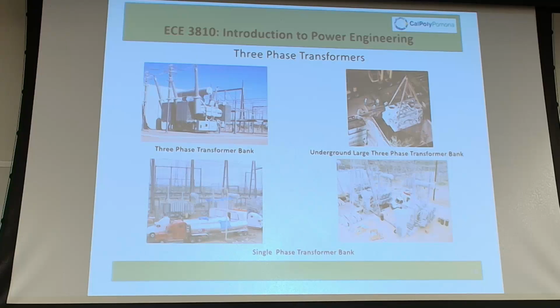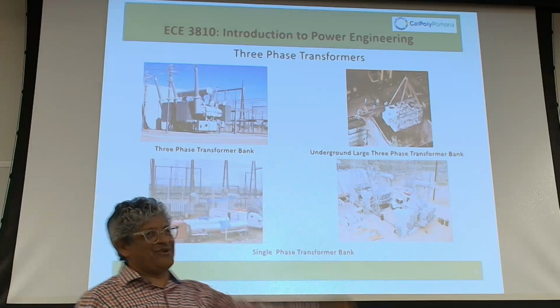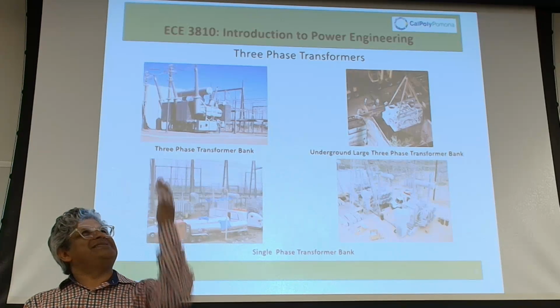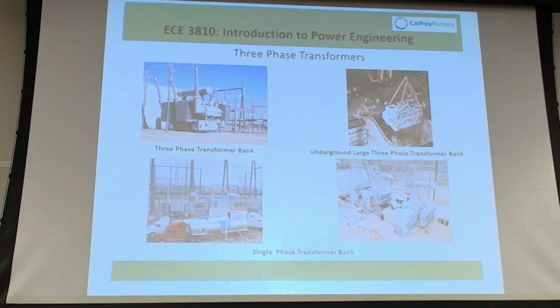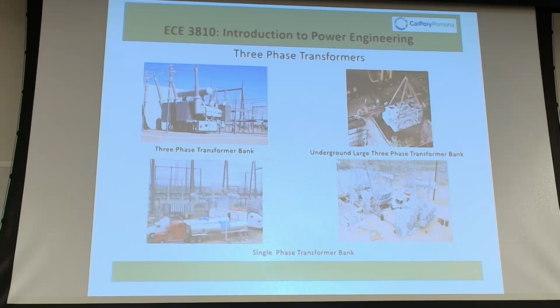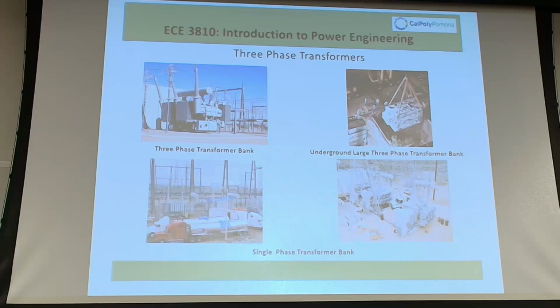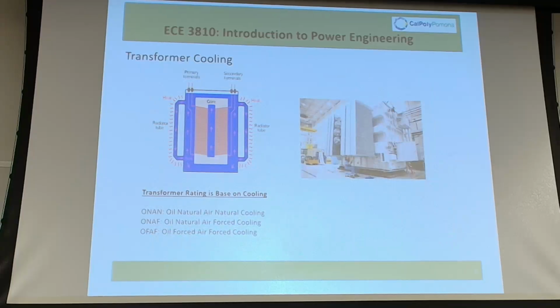And you'll see things that look like transformers. They look exactly like transformers, but there's only one insulator, and you go, oh, I see a primary, where's the secondary? Those are reactors. Because the underground cable produces a lot of VARs, you need reactors to absorb the VARs because of the capacitance of those lines. But the design is very much the same.